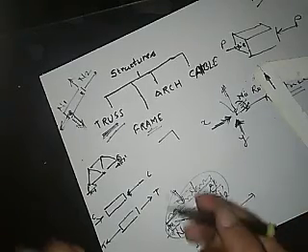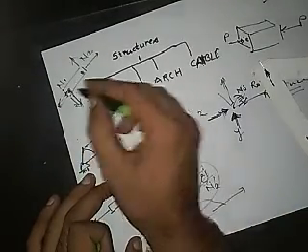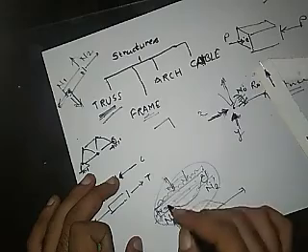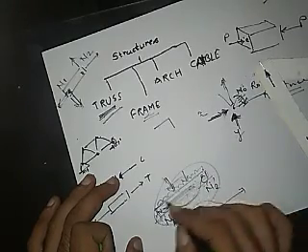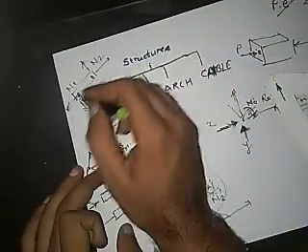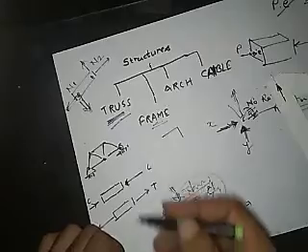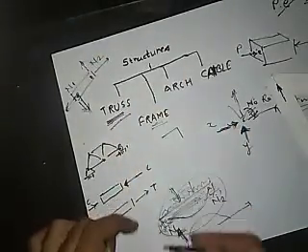And there will be a question: what happens to the self load of this, since this is being bent? Its self weight is bending it. But what about this? We are avoiding that. It is purely axial, and there will be only axial stresses whenever we construct it.